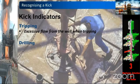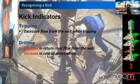What is the kick indicator during drilling? You will have an increase in the return from the well. You will have an increase in the rate of penetration. You will have an increase in the pit volume. The level in the mud tank will increase over time because we have flow from the formation.